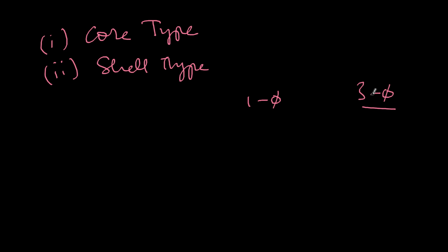So there will be three windings, not two windings. In fact, there will be six windings: three windings on the primary side, one for each phase, and three windings on the secondary side, one for each phase of the three phase, and so on. Whereas in one phase transformer there will be two windings. You can also use three one phase transformers to build a three phase transformer. So that you can actually work it out yourself.